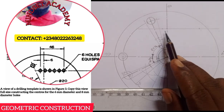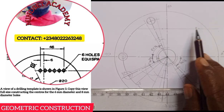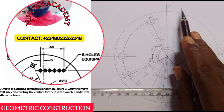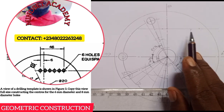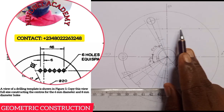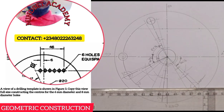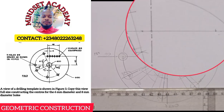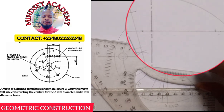If you move this, the 6 circles times 6 is what? 36. Now, if you subtract 36 from 46, you are left with what? 10. It means that for each of the circles, the space between each other is what? Is 2. So from the first point here, I will be measuring 2 millimeter apart.